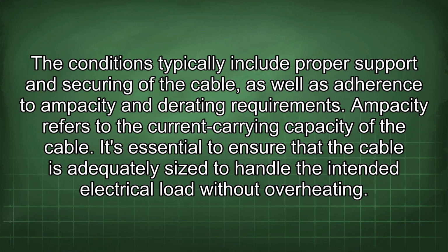The conditions typically include proper support and securing of the cable, as well as adherence to ampacity and derating requirements. Ampacity refers to the current carrying capacity of the cable. It's essential to ensure that the cable is adequately sized to handle the intended electrical load without overheating.